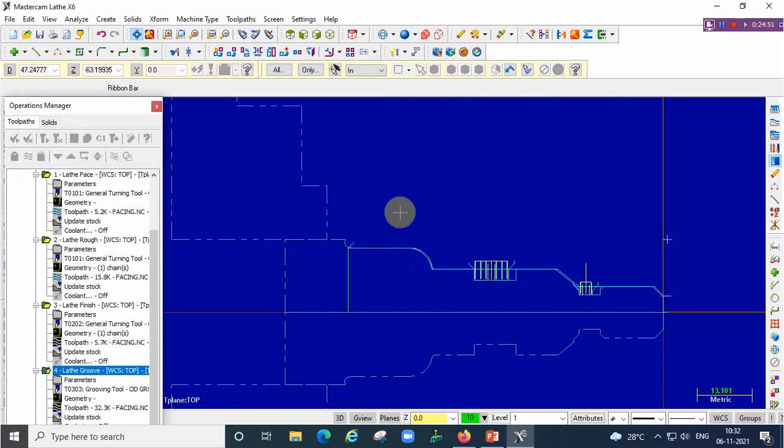And then, say that the error is coming. Why? Because the width of the tool we have to change. See, the width is different, so we have to select a minimum width of the cutter, so that is why the error is coming. Or otherwise, separately we can perform this operation.